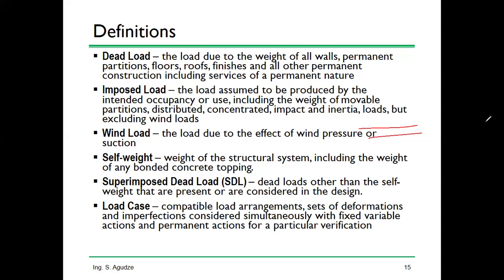Okay, let me leave the ceiling for now. But the plastering, they are all superimposed dead load. Usually you see that they are finishing more or less applied to the structural elements. So let us note that superimposed dead load and self-weight, they are all dead loads.